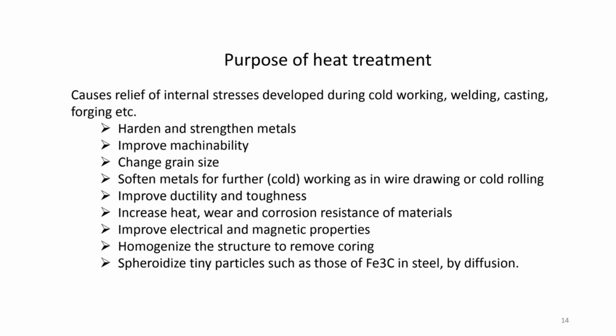It improves ductility and toughness. It increases heat, wear and corrosion resistance of materials. It can also improve electrical and magnetic properties. It can also homogenize the structure to remove coring, and it can spheroidize tiny particles such as those of Fe3C in steel by diffusion.